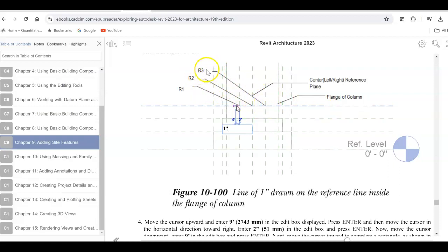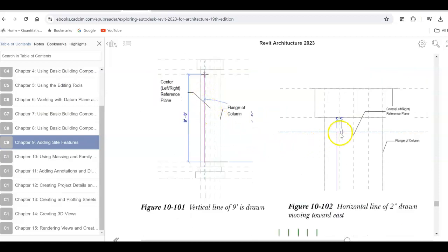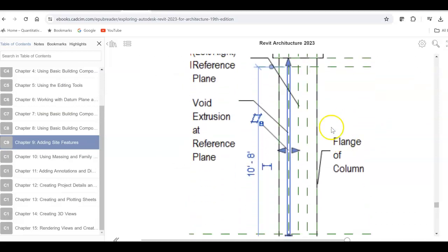So if we wanted to use that name tool, we could have named them. And then we're going to go up 1 inch, and then we're going to make a 2 inch gap. And with that, we're going to create, you could use a rectangle tool, but we're going to use a line tool so that you create one full area that you can create a void with.